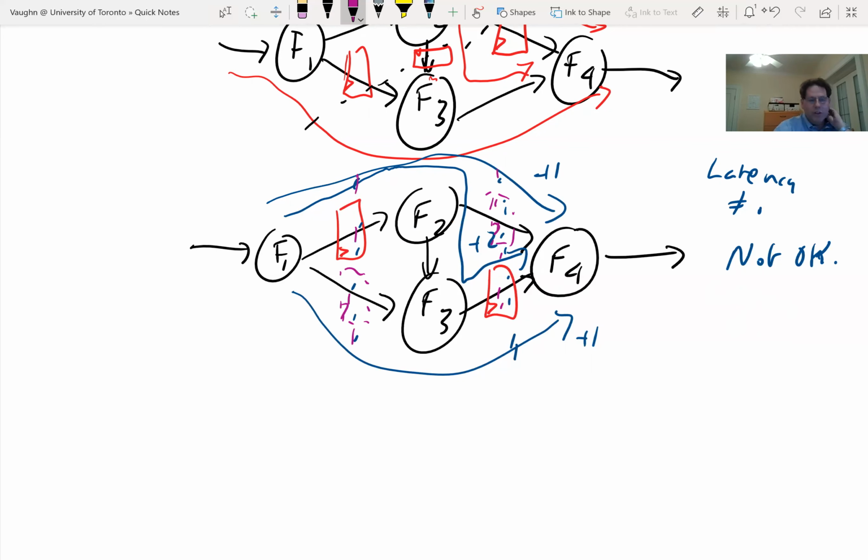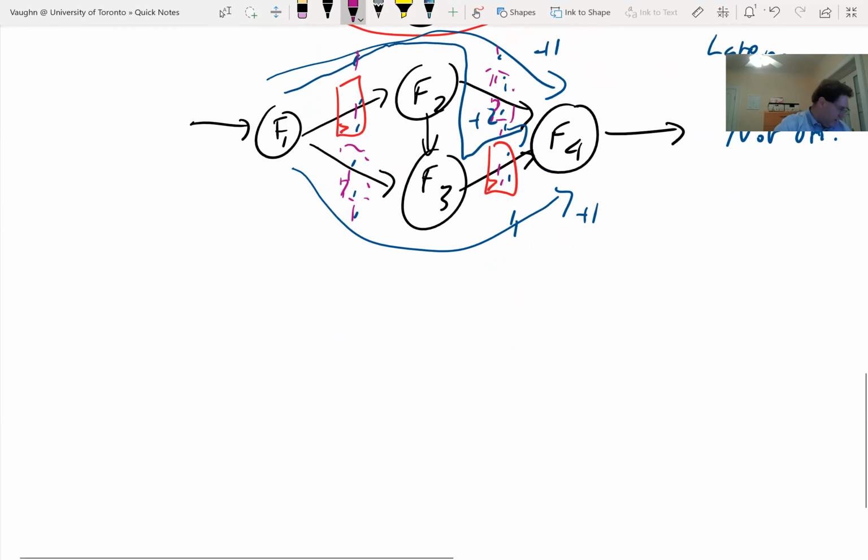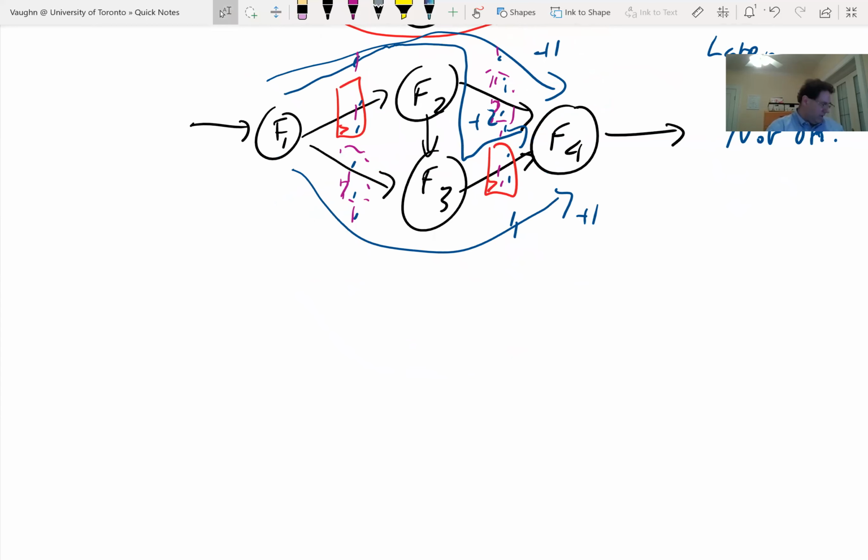You can pipeline over and over again, increasing latency by 1, then by 2, or equivalently for this special case of a feed-forward design, you can put more and more cuts in and put pipeline registers on all the edges cut by each of the cuts. And your circuit tends to get faster and faster. In an FPGA, because it's so register rich, in an ASIC you might go, should I really put all those registers in? There's an area cost to them, and maybe I've overdone it. In an FPGA, you have to pipeline a lot before it starts costing you area because it is so register rich. So you can tend to pipeline even more deeply than you do in other hardware structures.